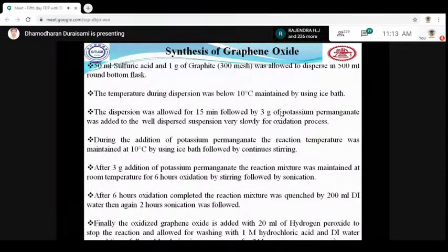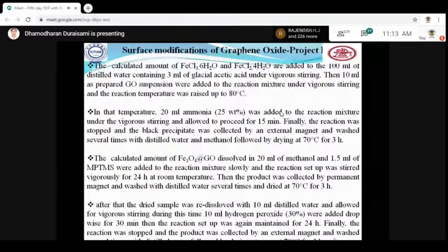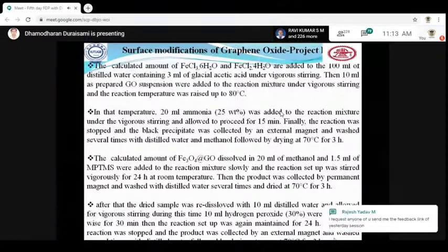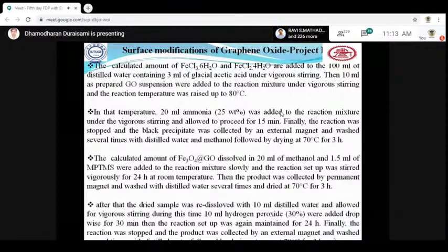So what we found is that generally when we work with graphene oxide, it has a possible nature of getting agglomeration. So what is agglomeration here? The graphene sheets have a layer by layer structure. Each adjacent layer has a van der Waals force of attraction between them. What will happen if we keep the graphene oxide simply? The graphene oxide sheets will get agglomerated, restacking, and then it will become a bulk. Once it becomes agglomerated, we cannot get better properties because it cannot make a better bonding formation with our matrix system.